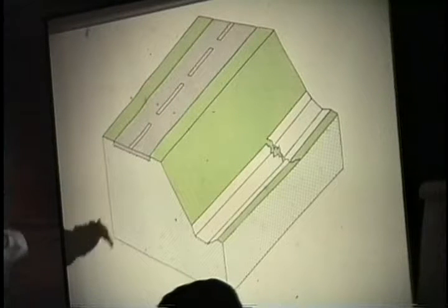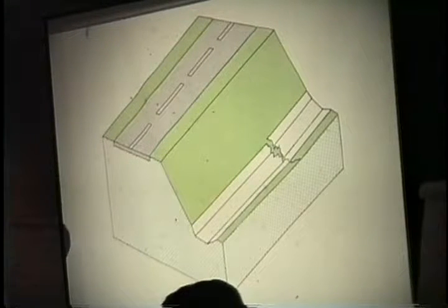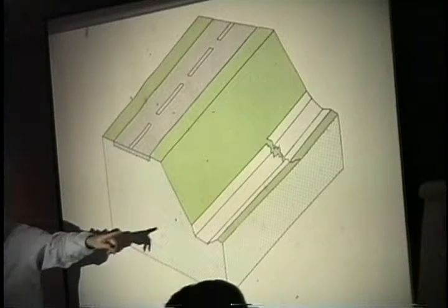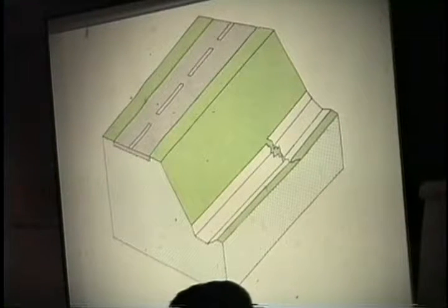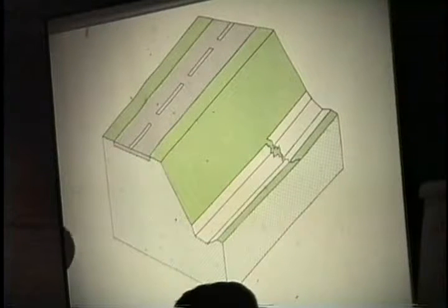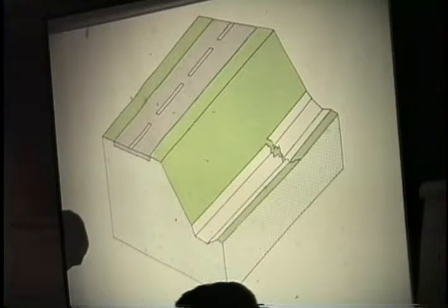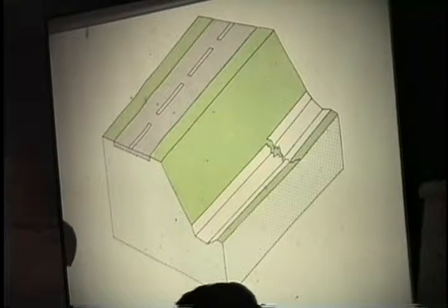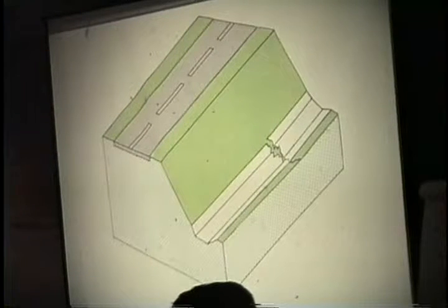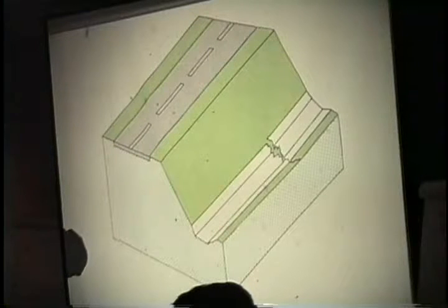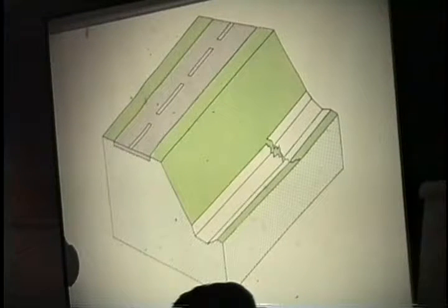And it would be worthwhile lining the ditch with fabric, because as water flows, even though it's going through the riprap, the riprap is mainly holding that surface down, holding the fabric down. And the purpose of the fabric is so it doesn't suck the soil below it out.